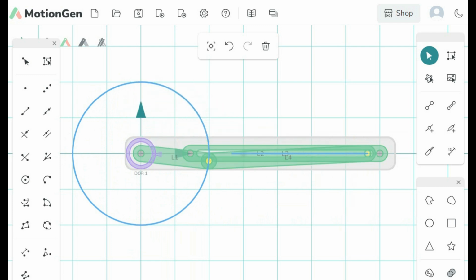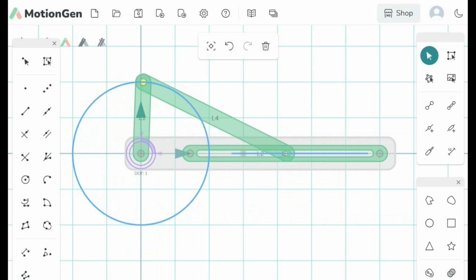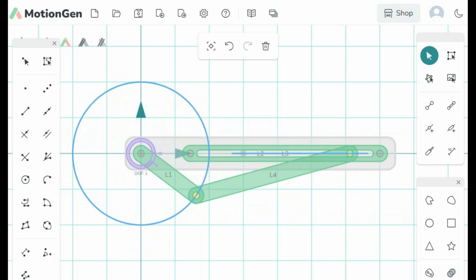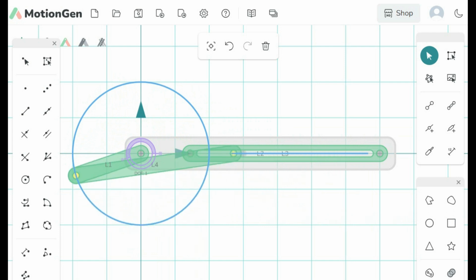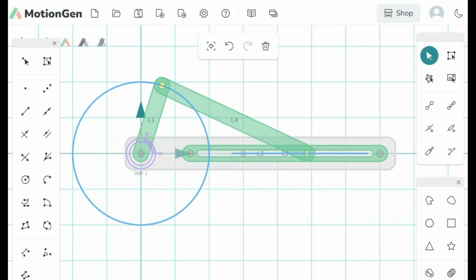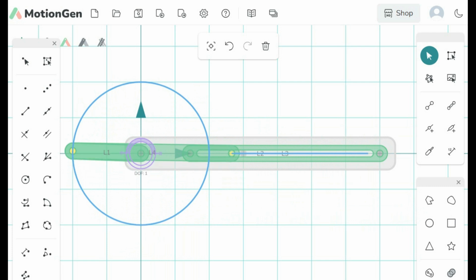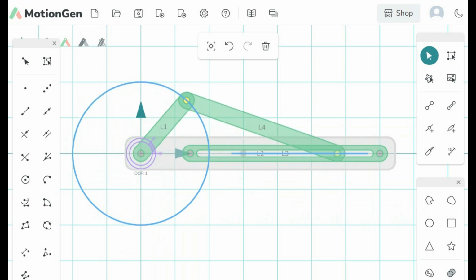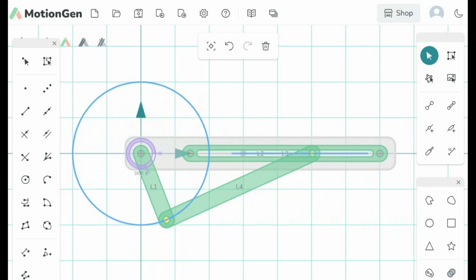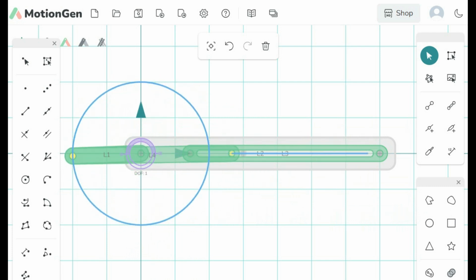One is you have to have a slotted link, as shown on the right. And the other thing, when you add the rotary motion down there, if you want to change anything after you initially add it, you're going to have to click on one of those dots beside the circle of the rotary actuator. It's about the only tricks I think you need to know to do this particular mechanism.